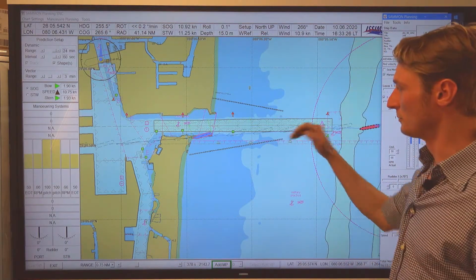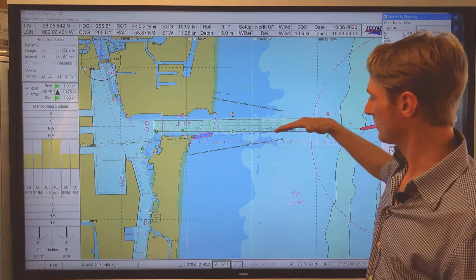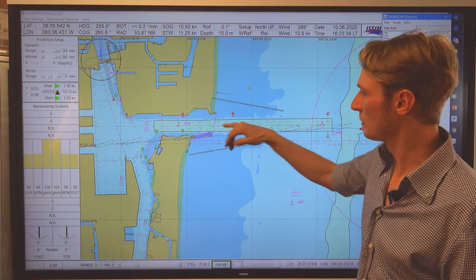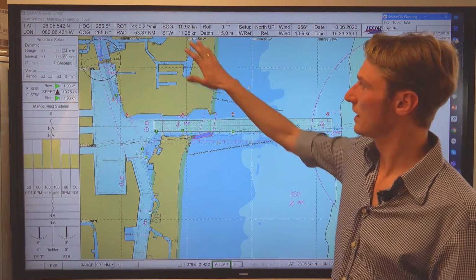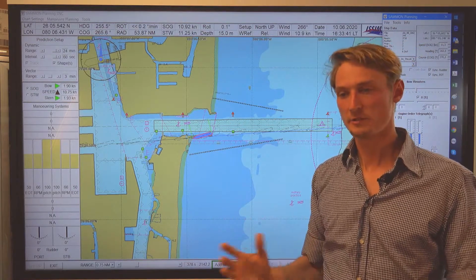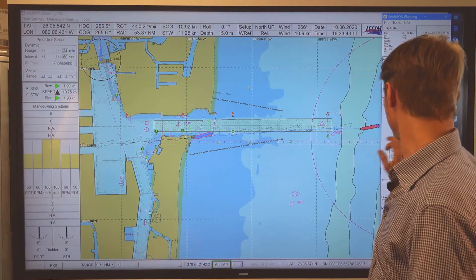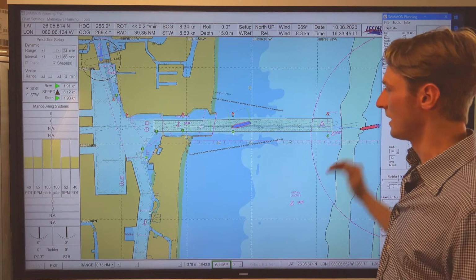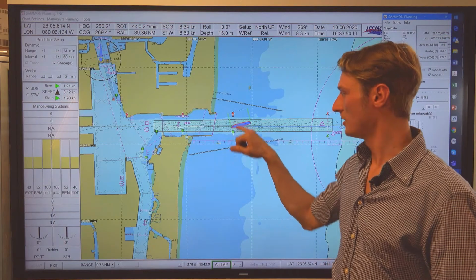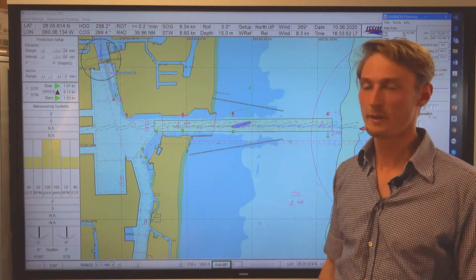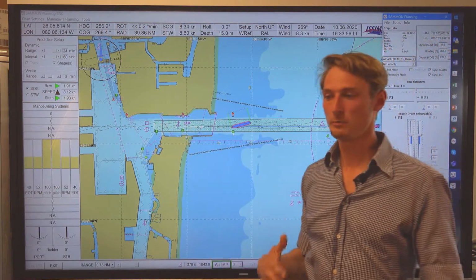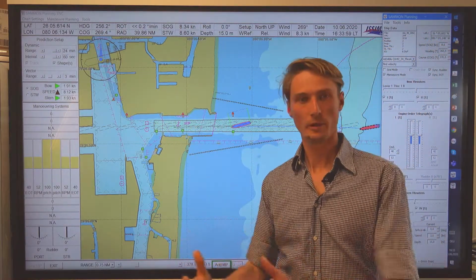On set 5 on both, my crabbing angle or my drift angle is less, and I will end up with a speed of 10 to 11 knots here at the breakwater. So our task is to stay between 8 and 10 knots. So let's go back to set 4. And we sail through the sea channel with these 10 degrees of drift angle until we reach this pair of buoys. Now we have the situation that inside the breakwater we will meet the calm water without any drift.